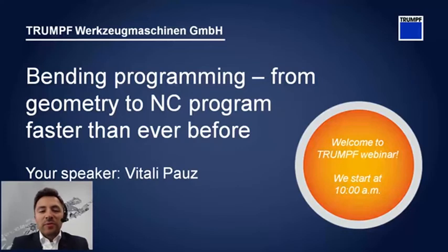In this webinar you will learn how to use the new direct editing functions within Bend and how to take forms into consideration and how to use the appropriate bending strategies in order to create practical NC programs. We will also learn how to add special tools and special materials. Thus, the bending sequence, the tool setup and the backgauge finger strategies of unfolds can be optimized for production